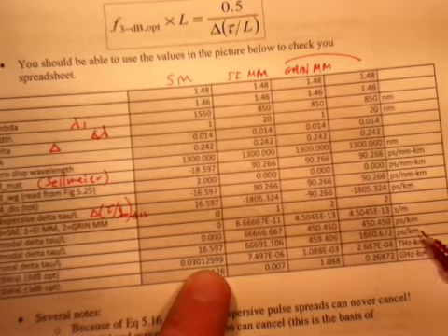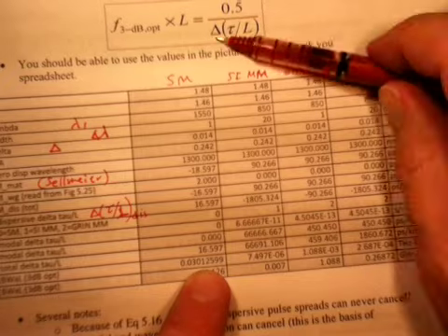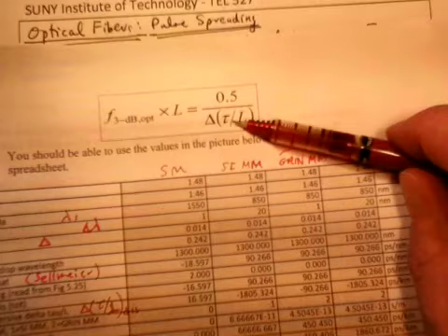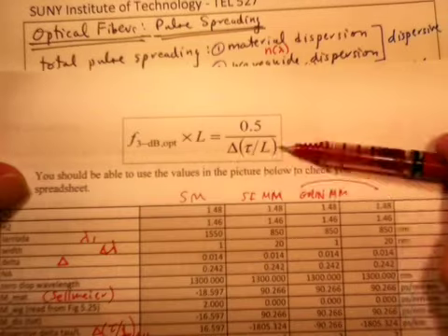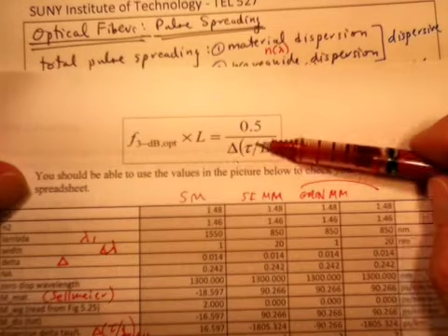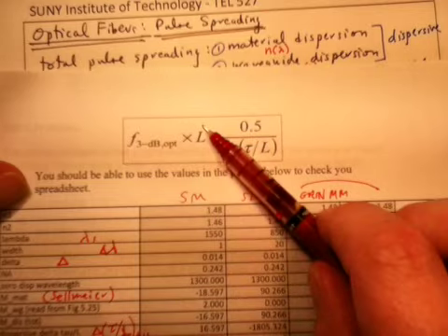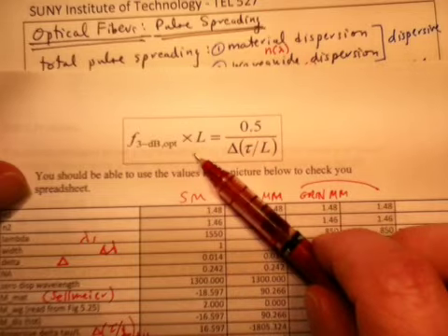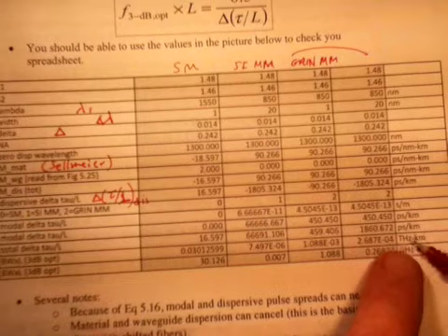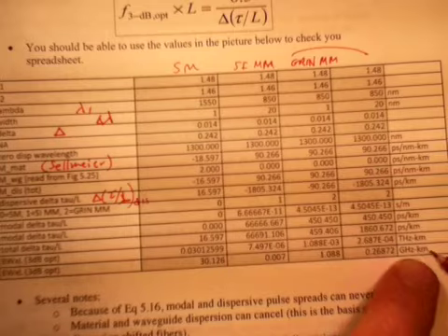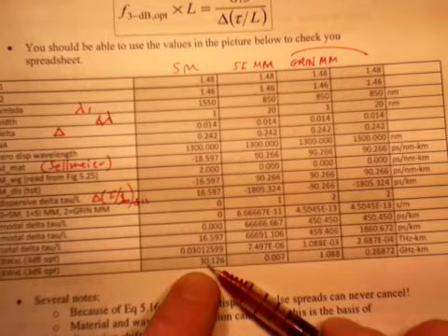So if I just plug in the delta tau over L in this equation with units picoseconds per kilometer, out comes kilometers per picosecond or terahertz kilometers. If I divide that by 1,000, I get gigahertz kilometers. And that's often useful to put